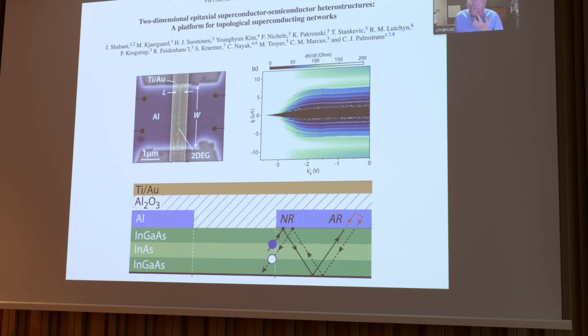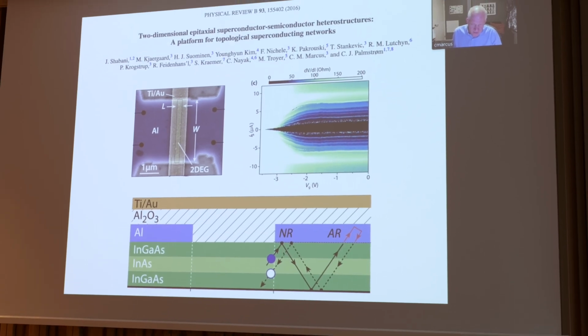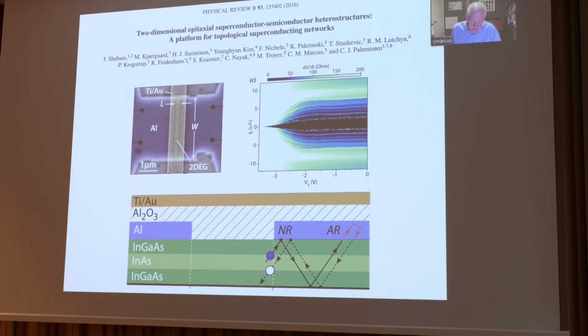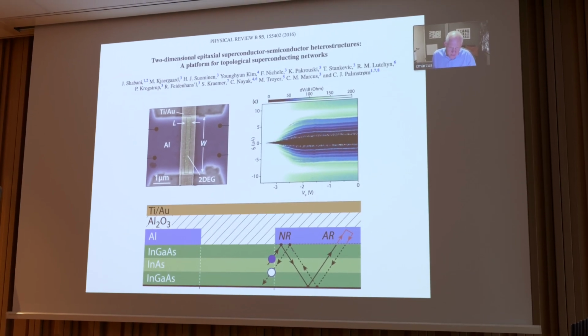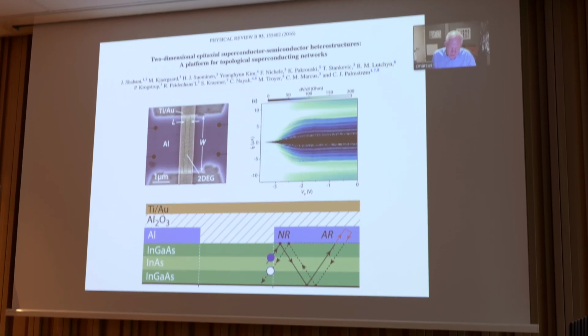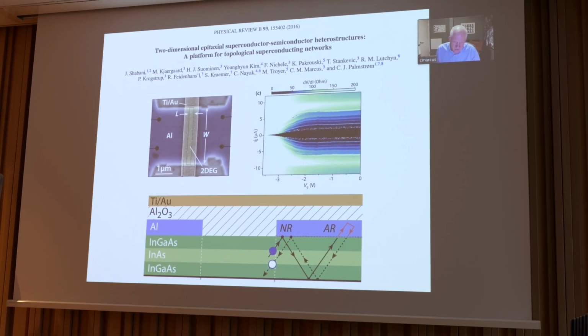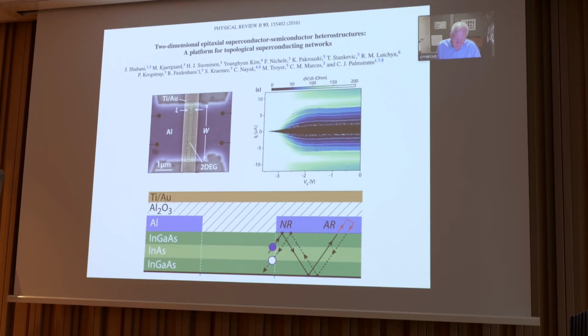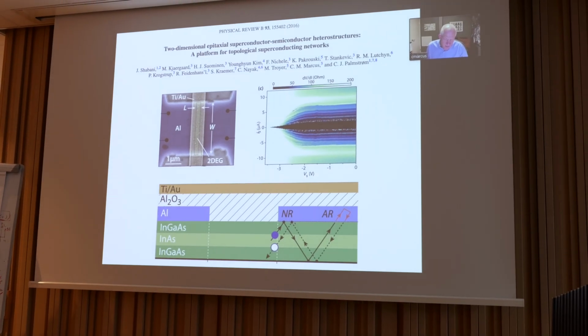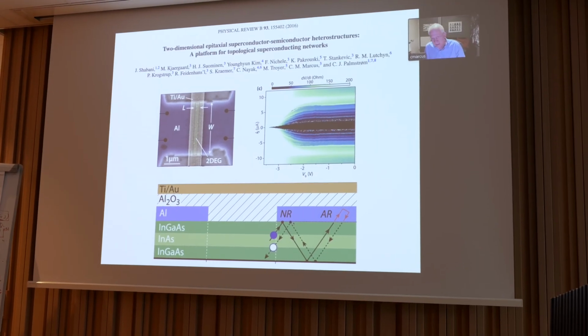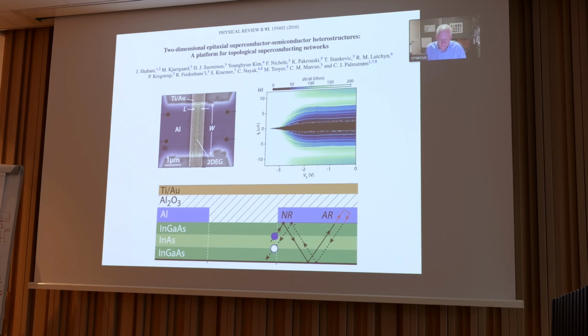And there was a lot of theory developed about how the transparency was so high, how in fact the reflection from the interface is, rather than being a simple high transparency reflection, a multiple bounce, as many tries underneath the semiconductor to convert from an electron to a hole. So it accounts for an overall very high transmission coefficient, near unity. And the signature is that the induced gap in the material is nearly as large as the gap of the superconductor itself.